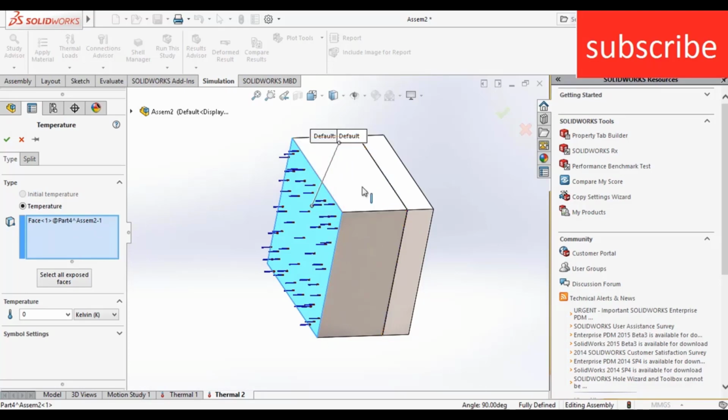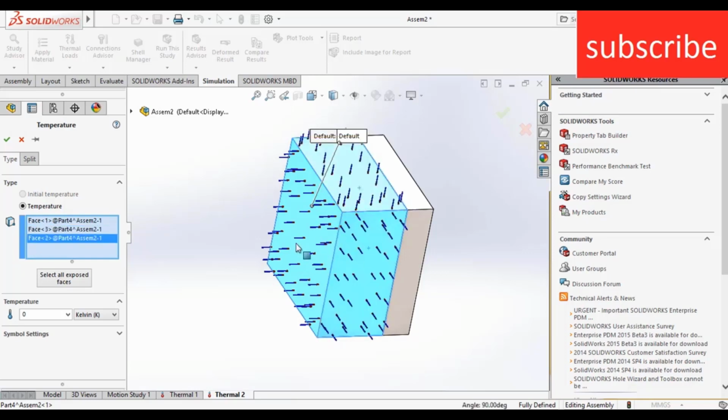For example, if I select this face, now my simulation becomes 2D, and I get a different value of Q at different points. It will not be the same all over the points because now my simulation is 2D. If I select all three faces, my simulation becomes 3D and I will get a different value at every point, even on the inside. So choose as per the requirement. Here I am just showing a simple 1D simulation.